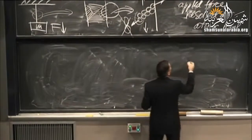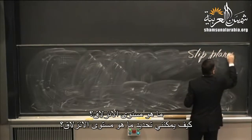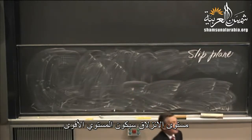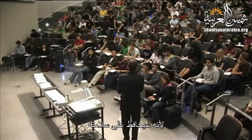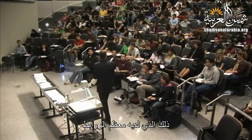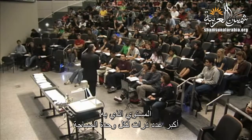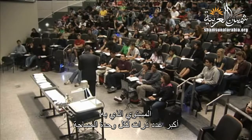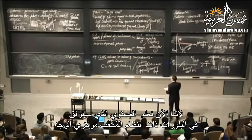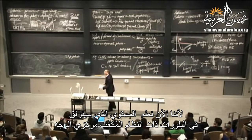All right, so this is... And what's the slip plane? How do I determine which is the slip plane? The slip plane is going to be the plane that's strongest because it retains its integrity. So which plane will be the strongest? The one with the most bonds. And which plane has the most bonds? The plane with the highest number of atoms per unit area. And that's why we study this stuff. Because now we know in an FCC crystal which plane will slide.